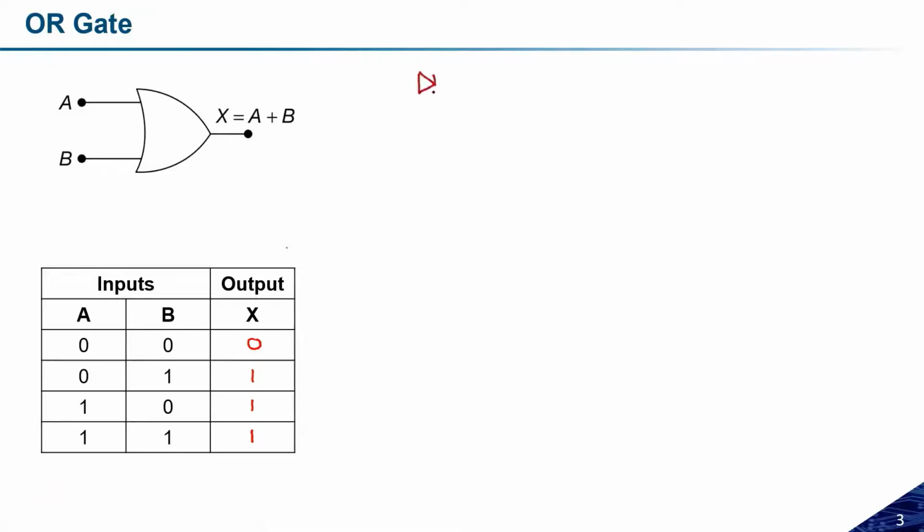If the potential is high, the diode will pass the current and act as an on state, with very small resistance. But if the logic 0 is here and logic 1 is there, the diode will be in the off state, or the resistance is very high. We know the concept of forward bias and reverse bias.